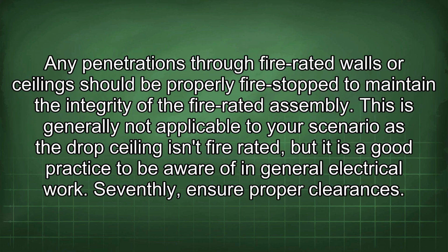Sixthly, consider fire stopping. Any penetrations through fire-rated walls or ceilings should be properly fire-stopped to maintain the integrity of the fire-rated assembly. This is generally not applicable to your scenario as the drop ceiling isn't fire-rated, but it is a good practice to be aware of in general electrical work.